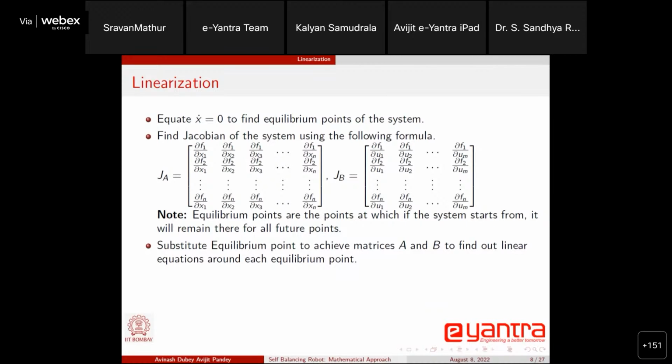Now, if you discretize your system, the system changes into the discrete time domain, and the imaginary line in the complex plane gets converted to the unit circle in the Z plane. So the condition translates to this: for a discrete time stable system, your eigenvalue should be inside the unit circle. And if it is outside the unit circle, your system becomes unstable. So for stability in the continuous time domain, your eigenvalue should be in the left half of the complex plane, and for the discrete time, it should be inside the unit circle. Fine.